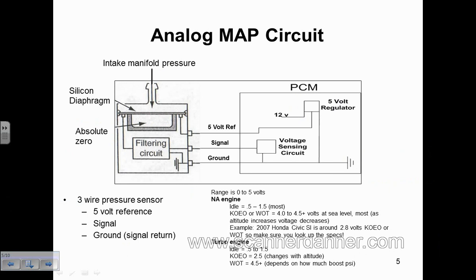When it comes to a MAP sensor, you need to understand that the MAP sensor, unlike the TPS, that's going to indicate closed throttle, the MAP sensor is actually going to indicate wide open throttle on initial key on. Because at wide open throttle, there's no vacuum. And key on engine off, there's no vacuum. So when you look at a MAP, you're going to see maybe 4.5 volts, initial key on. Then what happens when you start the car? It should drop. So is this a preliminary test we can use on any car on the road? Now, you're looking at the MAP, you understand how it operates, and you know when you start that car that MAP voltage should drop.